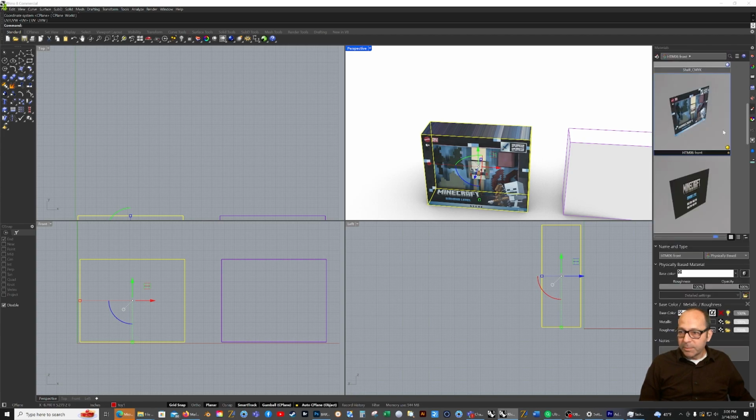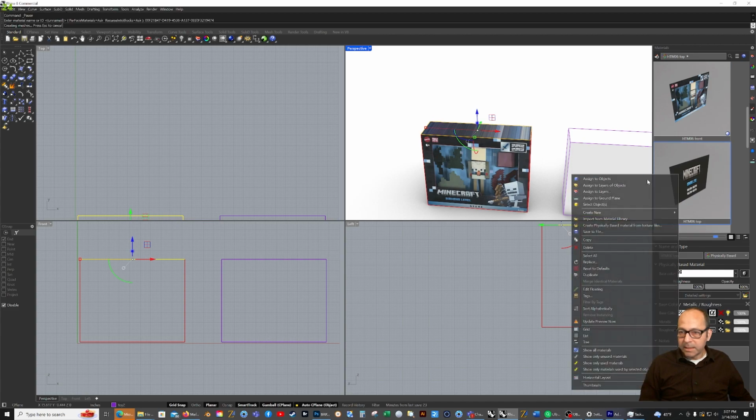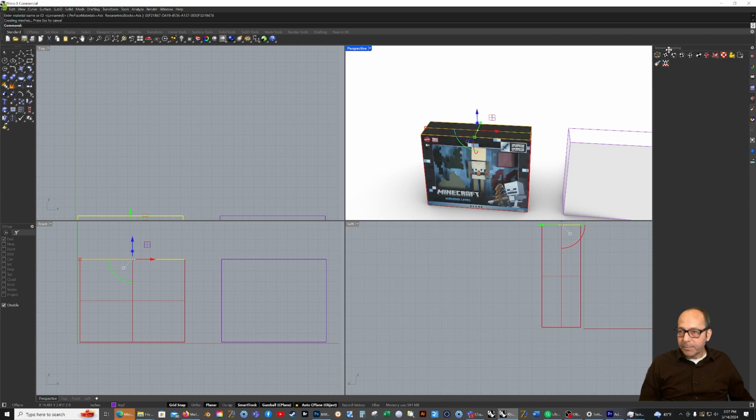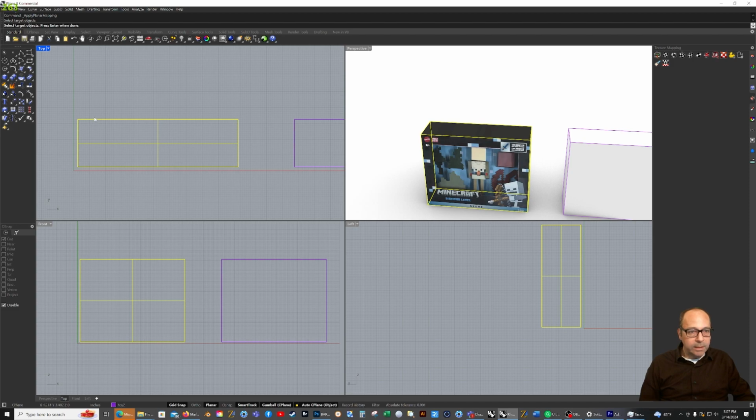Now the top does have a map. So I'm going to go back to my map, and here's the top for it, HTM06. So I'm going to do the same thing where I select that surface, right click, assign to objects, and then I have to do the mapping. Now this is going to be mapping channel 2. So I'm going to go to the top view. This is the object I'm working on because it was asking select target objects.